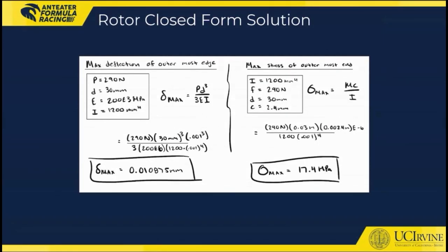This is the closed-form solution for the rotor. The theoretical maximum deflection and maximum stress are less than that of the simulation. This is because the theoretical calculation is not taking the fixtures into account, which will influence these values.